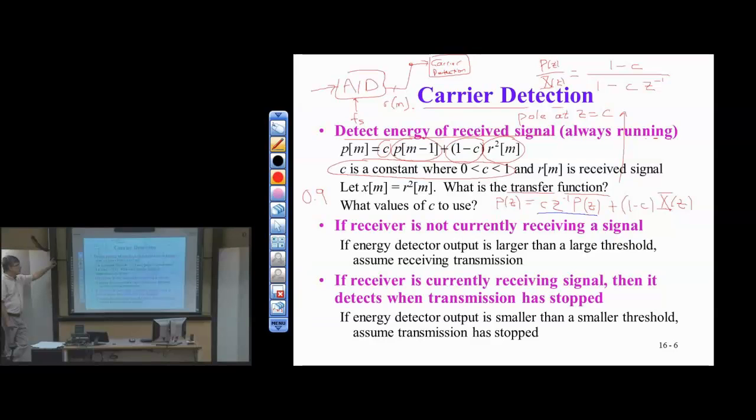We can replace the multiplication with a right shift if we're in 2's complement. Divide by 2, it's a right shift by 1. Divide by 4, it's a right shift by 2. 0.5, not bad, a pretty good choice.